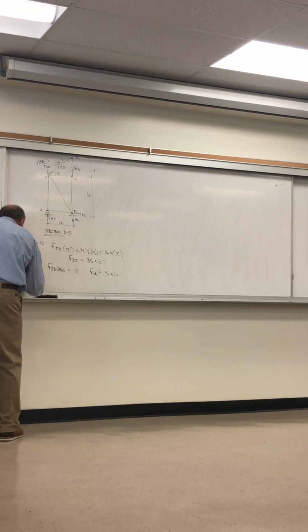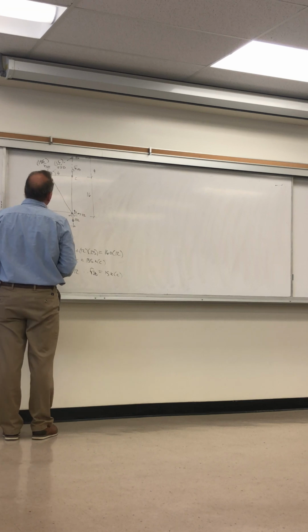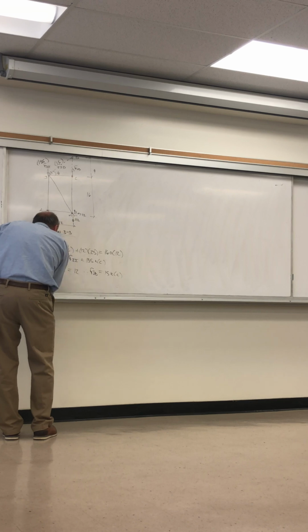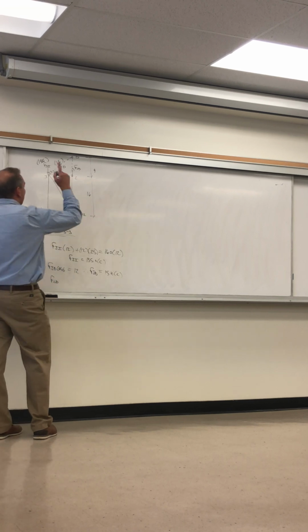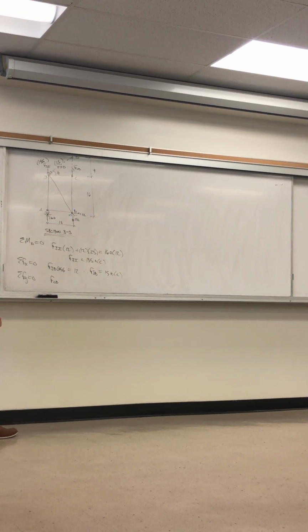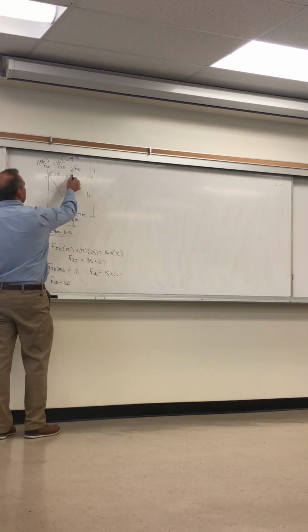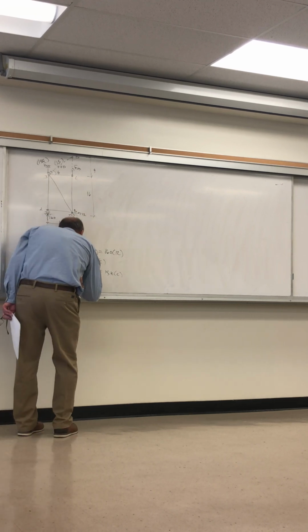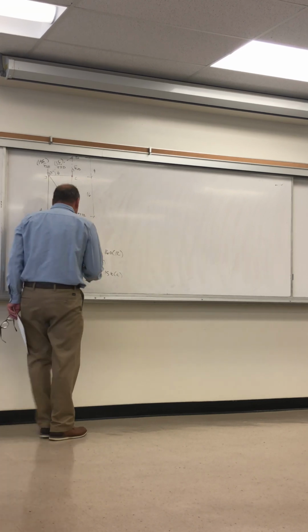Summation of forces in the Y. Our last equation available to us is 0. So I have F of CD, that's up, right? Plus 160 is up. That's the reaction to the left. This plus this equals the force down on the right, the reaction on the right side, 112.